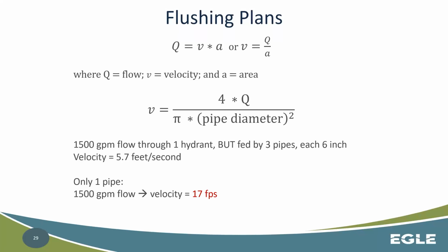So you just have to understand, when you're flowing these hydrants, how fast you're moving that water and what you're trying to do in that relationship. If you're just trying to see the absolute highest volume of water you can get out of this pipe in an emergency condition like firefighting, then you may have to find out if you can get to that 1,500 gallons per minute within that area. Usually if you're doing that without unidirectionally flushing, that's probably not such a big deal to the distribution system. The only part of the distribution system that's seeing that 17 feet per second is that 6-inch run heading to that hydrant, which is not a very large run typically and is fairly easy to replace if necessary, if it breaks down for some reason.